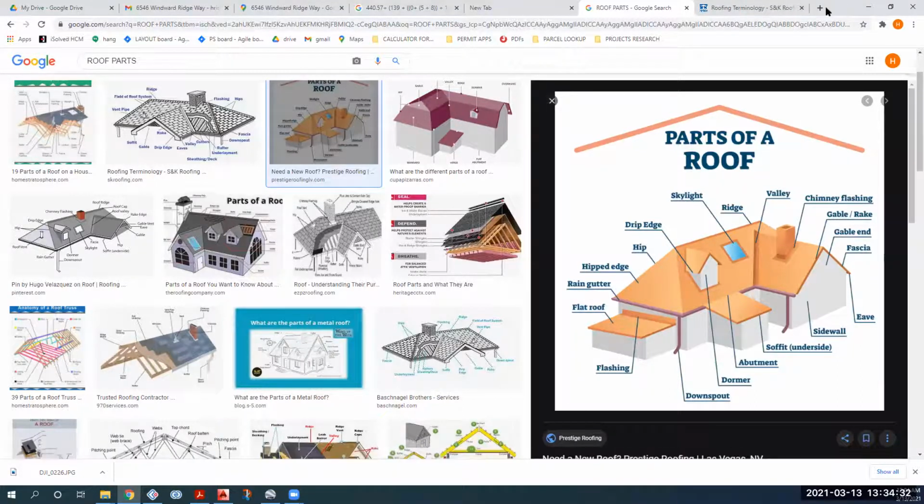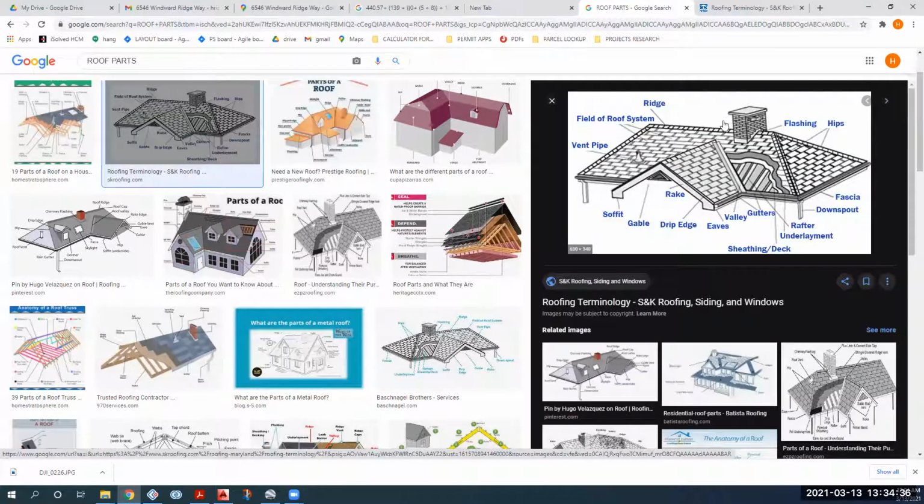However, what we are trying to do here is project those 3 feet on a slope. So when we see 3 feet projected from the top, it looks less than 3 feet. How much less it looks you can determine by multiplying 3 feet by the cosine of the pitch of the roof.